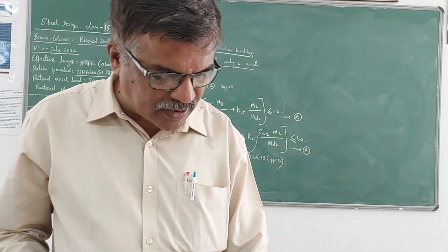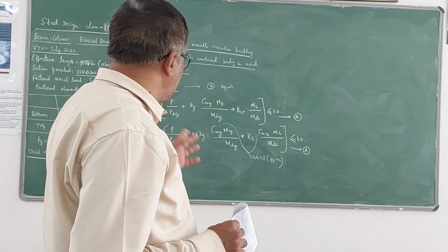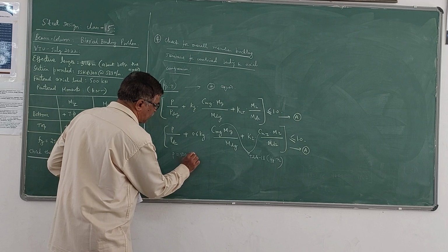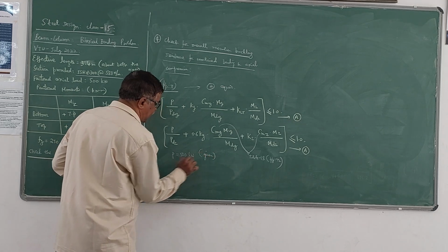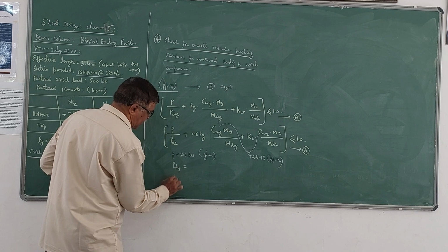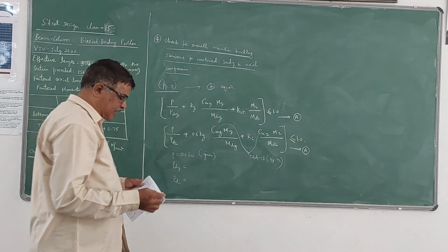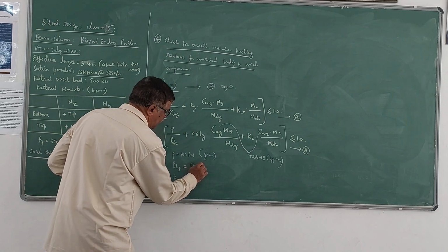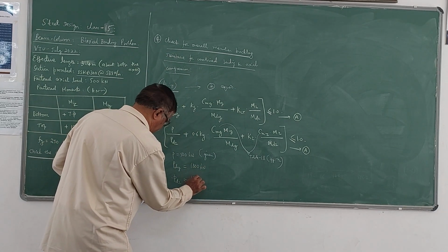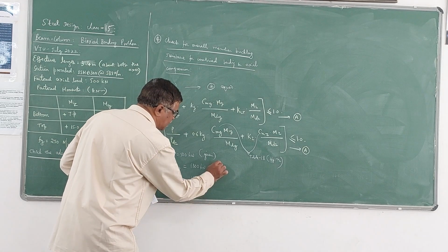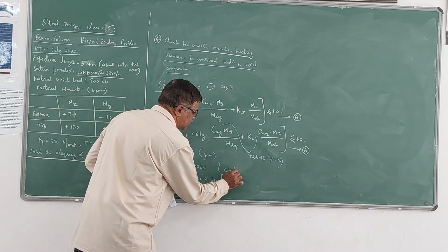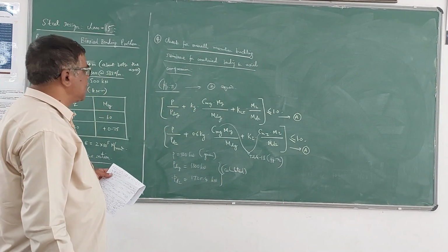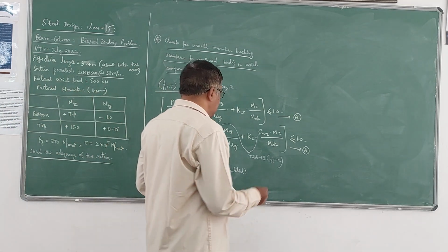Then P is the applied axial compression under factored load, which is 500 kilonewton. It is given in the problem. That value you take. Then PDY and PDZ we have already calculated in one of the earlier checks. The value of PDY is 1300 kilonewton, and PDZ is 1725.4 kilonewton. Then we need to find MZ, MY, and MDY, which are also known.